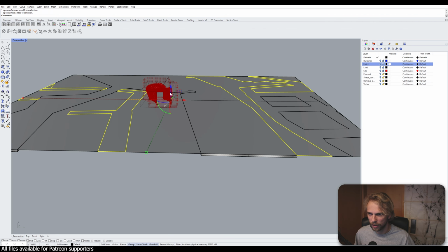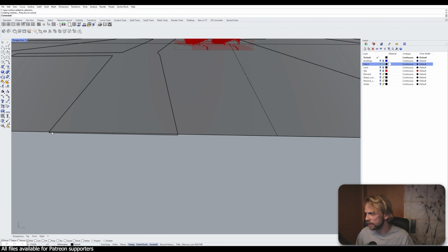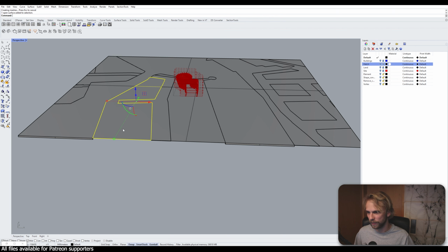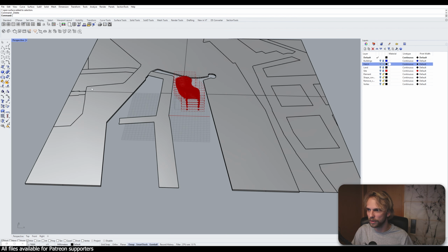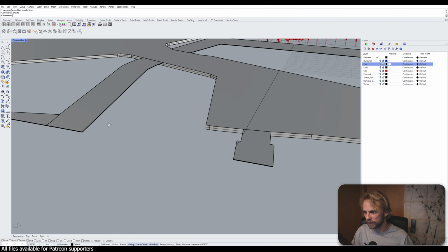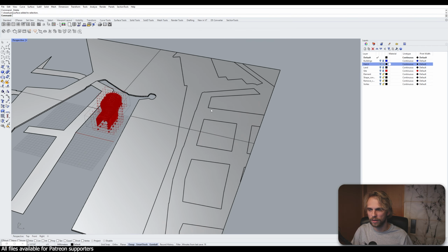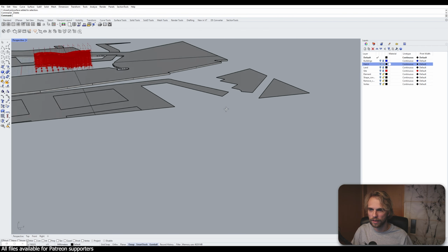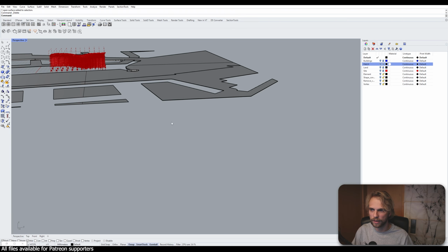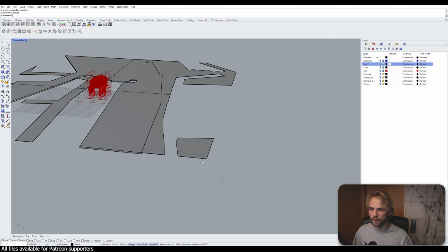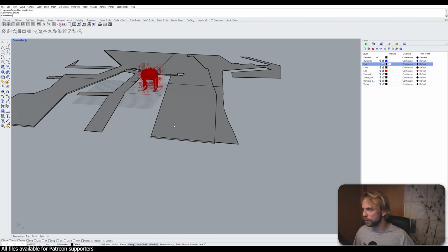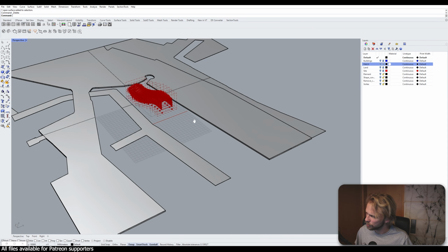They go down as well, and they get extruded down by minus 150, I guess, or let's do 200 millimeters. Very thin, but still that little shadow line is gonna appear, so it's important to do it. And then everything that's left is unimportant. We can delete it, and you will understand why we're deleting it in just a second. So for now we have that. Don't need that. Wait, no, we do need that. We don't need that, that, or that. And these are the building bases, so we don't care about those. All right, so I'm basically trimming away the corridors for the streets and the corridors for the water. The water corridor is 2 meters deep, and the street corridor is only 20 centimeters deep.